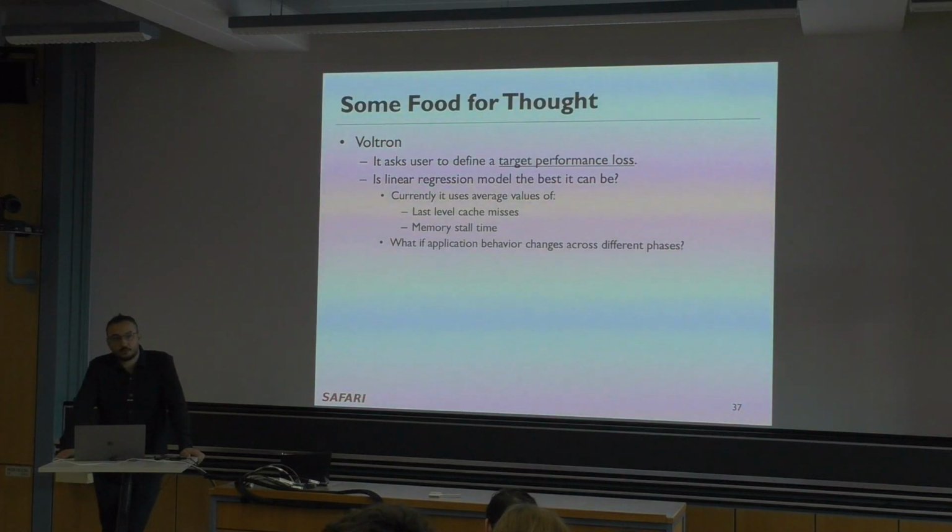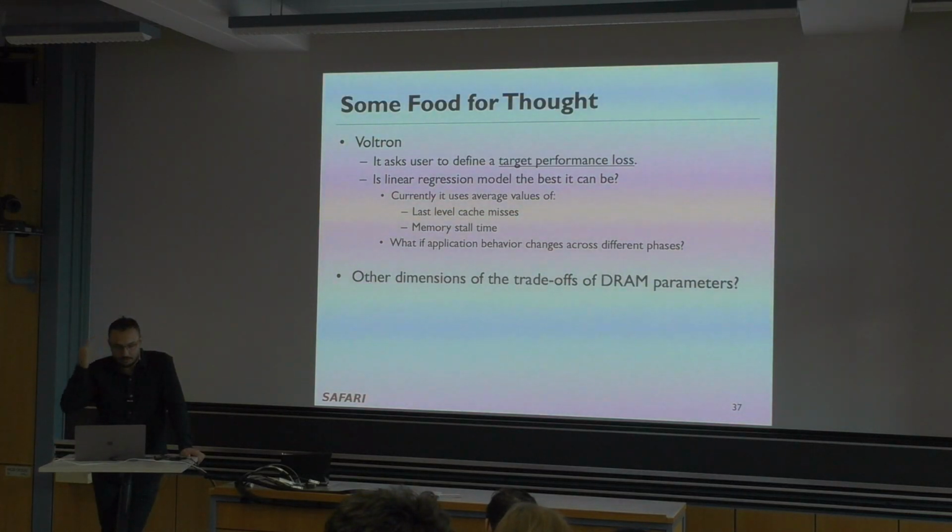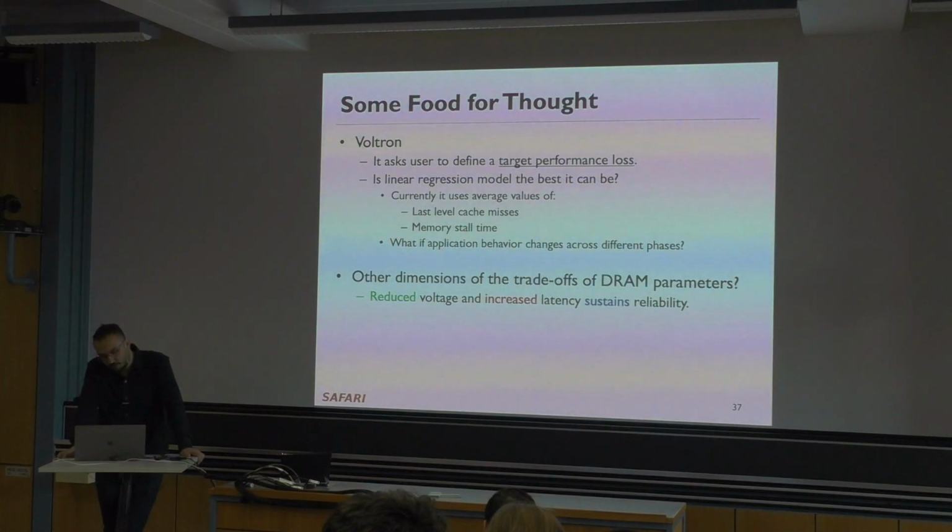If there's no other thought or question, I'll go and ask from another aspect. So here we see some trade-off of DRAM parameters, namely voltage and latency, and reliability. So this was our takeaway, right? Reduced voltage and increased latency sustains the reliability.